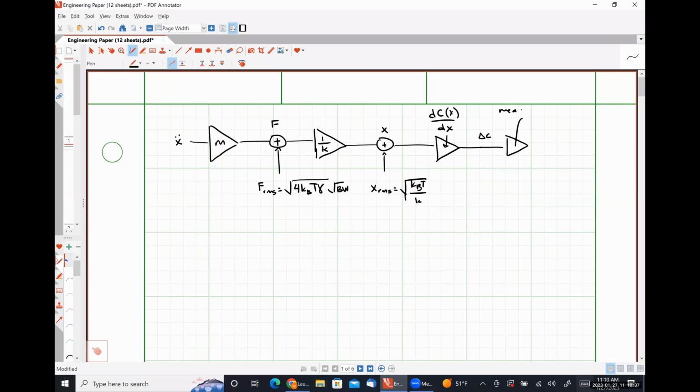And then this block right here represents our measurement circuit, so that we are effectively at our output voltage. But capacitors have some associated RMS noise voltage that is root kBT over C. I'm going to draw this out for you all pretty, but effectively you're going to analyze the system from tip to tail.